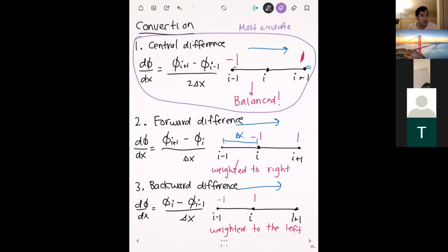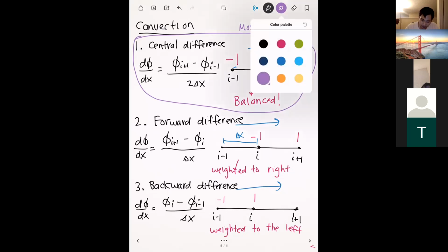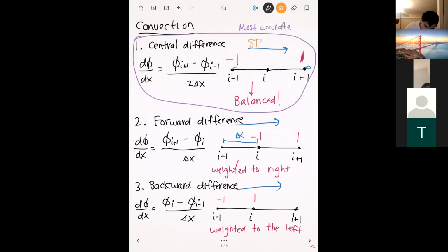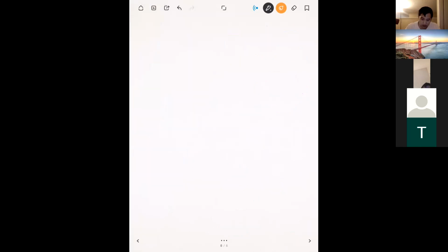Accuracy is good. If your simulation is accurate, then you did a good job and simulated reality really well. That's not a bad decision, and there are ways you can make the central difference scheme work. But once you start adding convection into your equations, there's another factor you have to consider besides accuracy, and that's stability. We'll go over what an unstable solution looks like later on in the notes. Keep this in mind, because next we're going to do an example, and I'll show you what happens when we use an unstable solution.